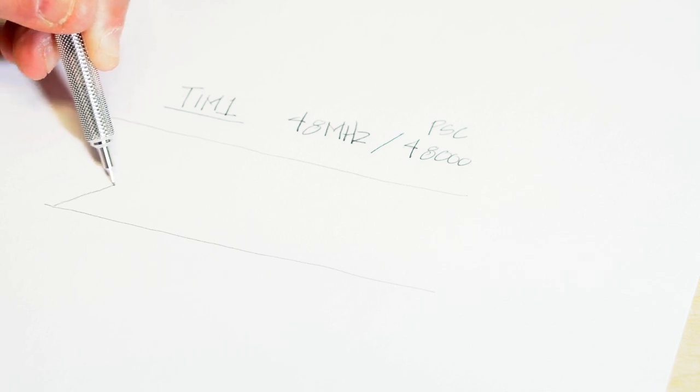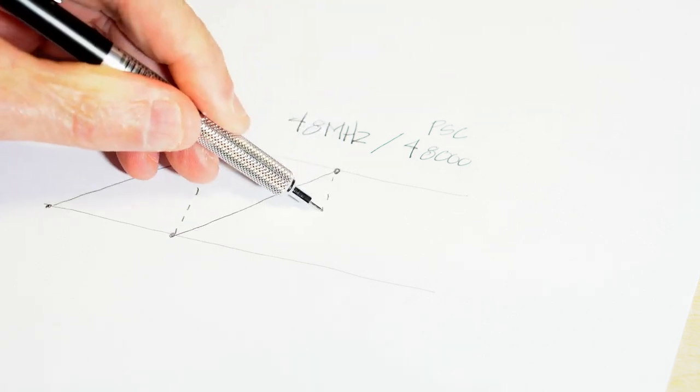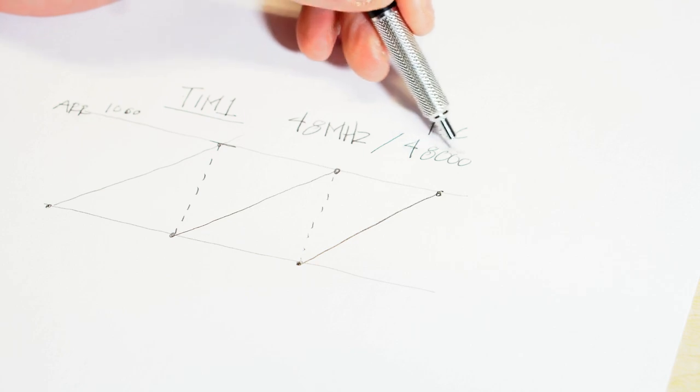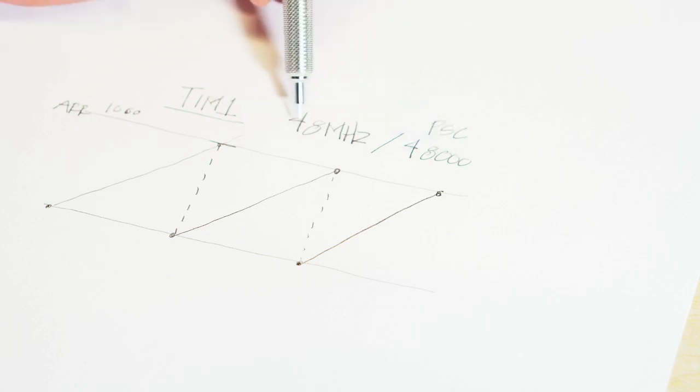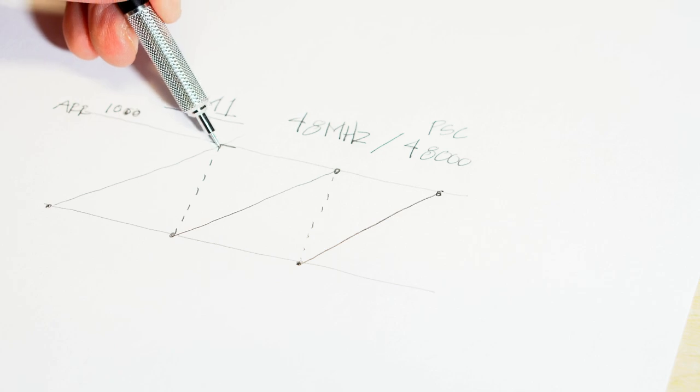What I want to do is make sure that there is a trigger in the timer that will tell me that it's reached 1,000. So we're going to create a sawtooth pattern here. The timer is going to be going up, and instead of it keep going up and counting indefinitely, we're going to use the ARR, which is this top level here. And the ARR is going to be 1,000. So when it's reached 1,000, it will drop back down to 0. And then it will count up again until it reaches 1,000. And then it will drop back down to 0. It'll count up again to 1,000. So at each 1,000, because we divided it by 48,000 at 48 megahertz, the timer 1 is counting at 1,000 pulses per second. So if we have a top value of 1,000, then we should get this trigger every second.